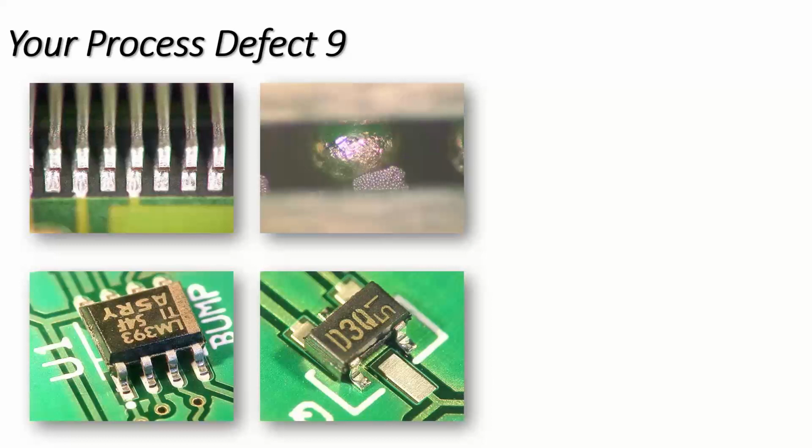But again, one of the things you can do is do a process simulation with solder on a board with a glass slide and watch what happens. There's a couple of paste manufacturers. I know that Kester did some work using this technique, which I use, and there's been a couple of others. So again, use a technique which allows you to understand and see this actually happening.